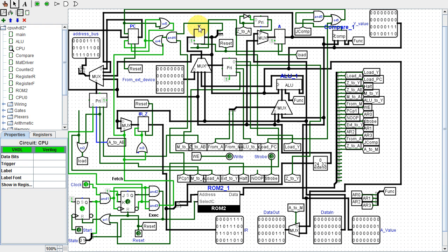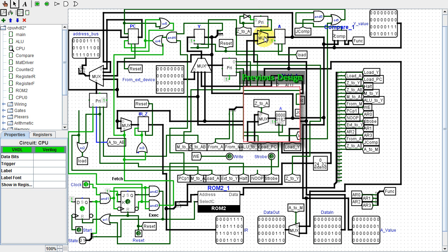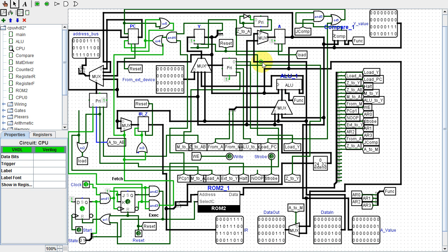While testing the VHDL program, I noticed the A register wasn't getting the right values. The design worked in Evolution, but not in VHDL. I figured out that if I put in a priority encoder to select the mux line, it would work. This seems stupid since it should work the same as selecting the mux line directly, but I guess there's something going on with gate delays or something.